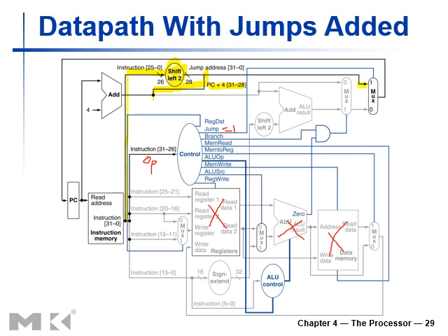So we have to assign the jump address whenever jump equals 1. If you see that jump equals 1, in that particular scenario the jump address will be assigned to the program counter. Otherwise, the other possibilities can be PC plus 4, or PC plus 4 plus label, in other instructions that can be assigned to the program counter.